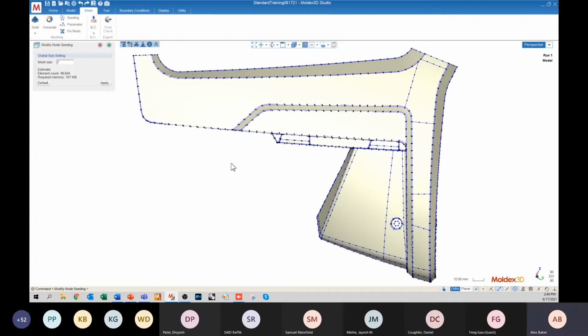All right, now as far as the Goldilocks method is concerned, what we're going to do is decrease our mesh size until there's about, and you'll have to hang with me on this, 2 to 3 nodes width of space between the black nodes. A node's width of space is actually just the thickness of one of these black nodes. So I want to be able to fit about 2 to 3 of these black nodes in the space between the black nodes. Hopefully that makes sense. And it's going to be more of a visual approach, which is why we call it the Goldilocks method and nothing more scientific, because it's not really scientific.